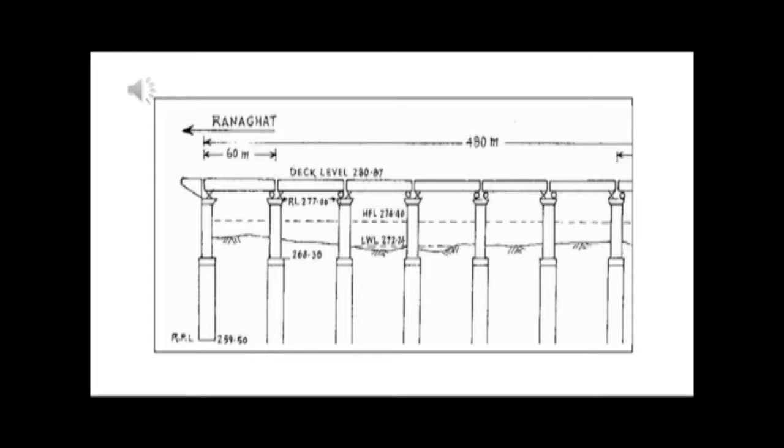The various stages of the river, with varying gradient at each level, give us an idea about the span of the bridge and bed profile, hydraulic data, scouring, and water levels, that is HFL, OFL, LWL. We also understand that when we are providing a foundation, we have to understand how much scouring tendency the water in that very stage of the river has.